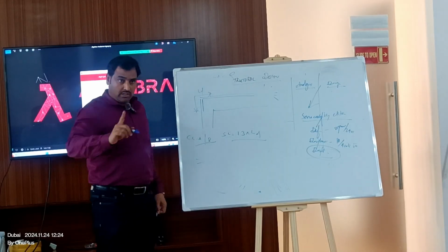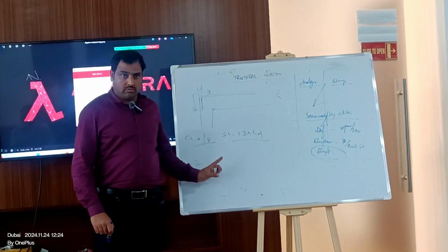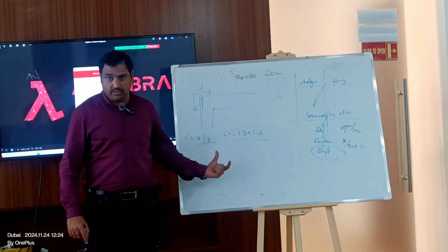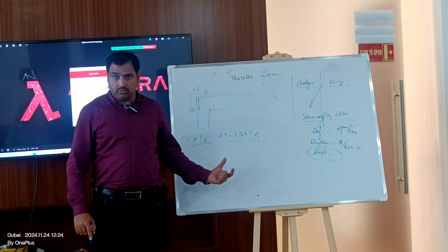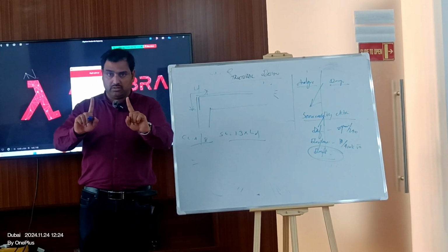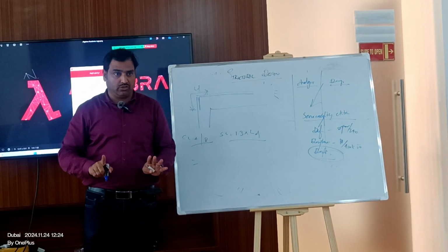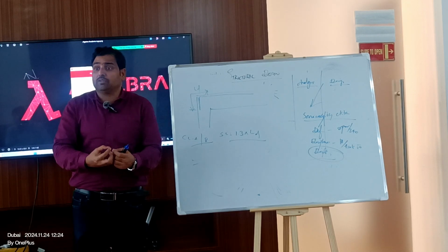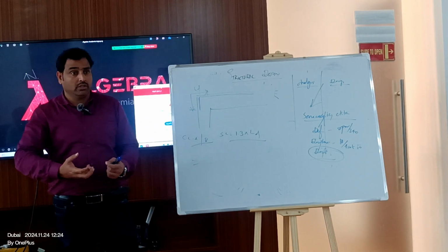It is class B rebar. In splice calculation, you do have 2 rebars, class A and class B. It is the same rebar. There is no change in the rebar. The performance of the rebar is different. The performance of the structural element is different.